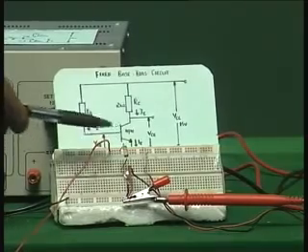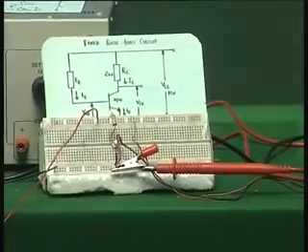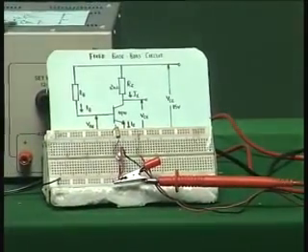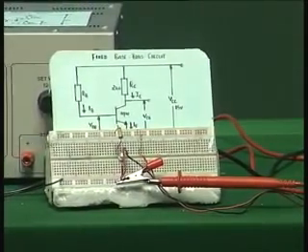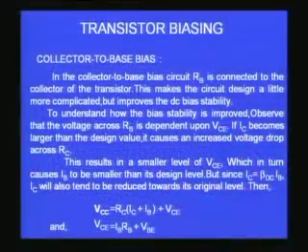So due to small variations in these, you are getting slightly different values of voltage or current, but this is quite possible in any given amplifier circuit, and these small variations in general will not make any great variations in terms of the performance of the amplifier. So now we saw one biasing circuit which involved a base resistor connected between the VCC and the base of the transistor. But there is another way of constructing a biasing circuit also, and I will show you on the picture.